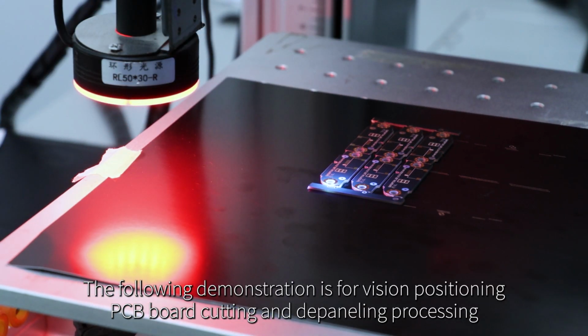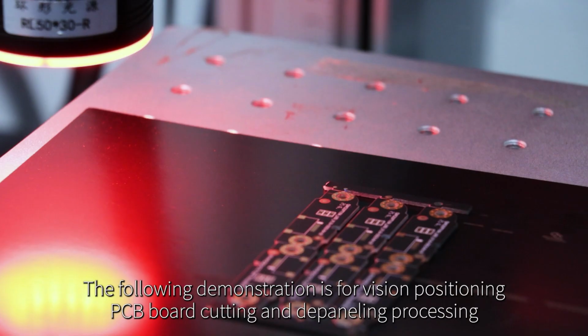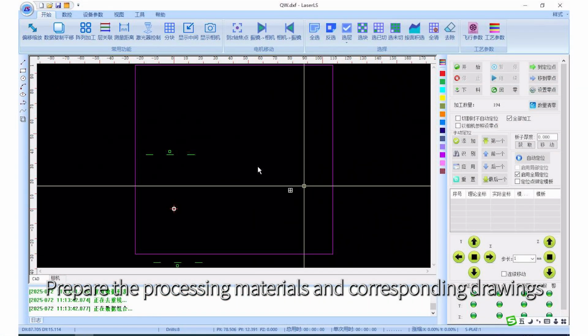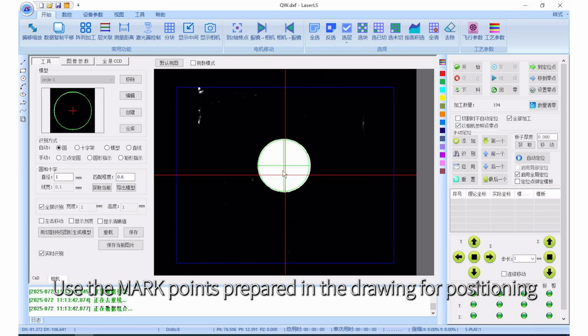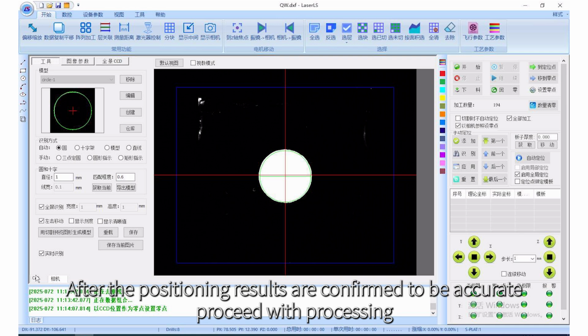The following demonstration is for vision positioning, PCB board cutting, and depaneling processing. Prepare the processing materials and corresponding drawings. Use the mark points prepared in the drawing for positioning. After the positioning results are confirmed to be accurate, proceed with processing.